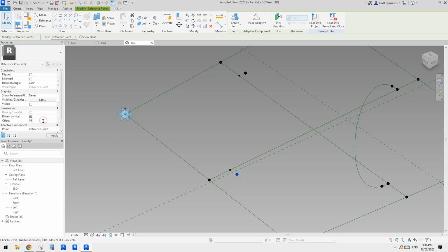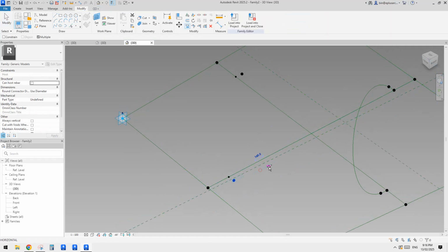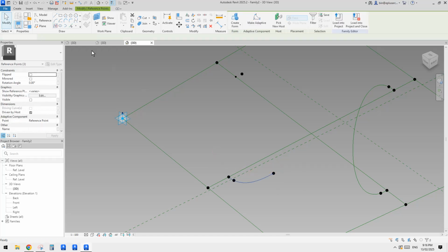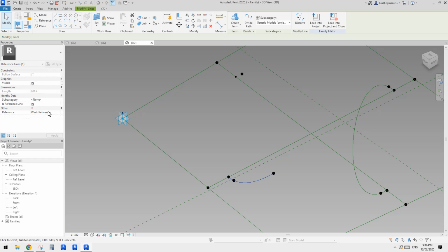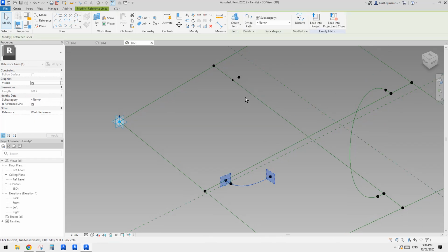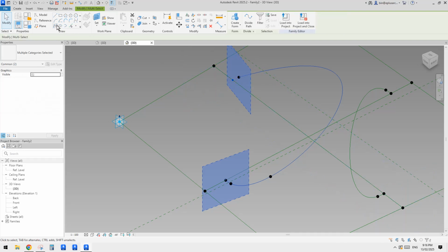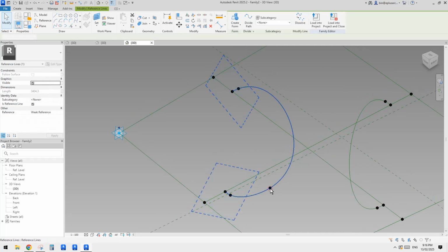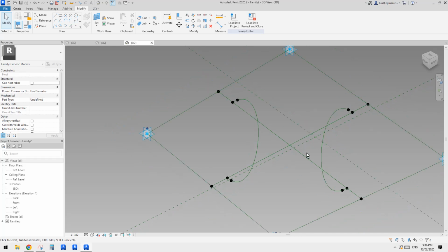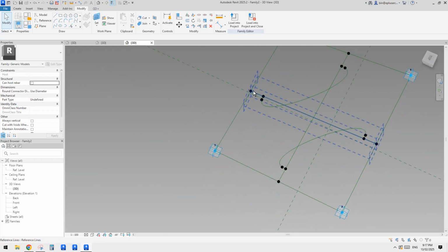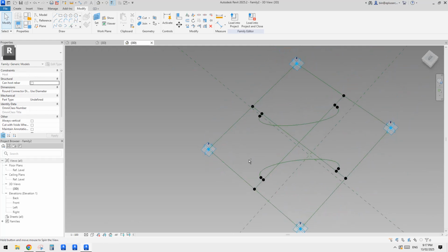Yeah, 100. Okay, for now. And then I'll just copy another point. Maybe just drag it here. Select 1, 2, 3, spline through points. Maybe just make a reference line. And select this line and then select this point. So it will go there, and select this line, spline and this point, create. Okay, so now we can delete this one. So now we have this, right? So this is the shape roughly.